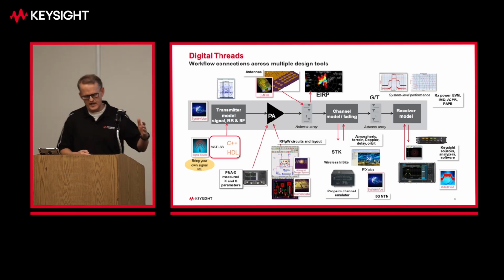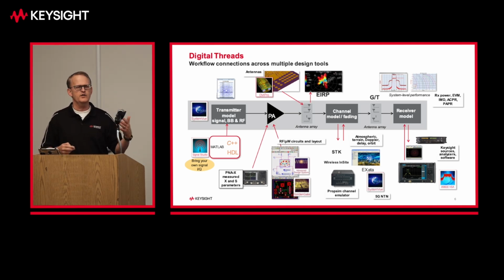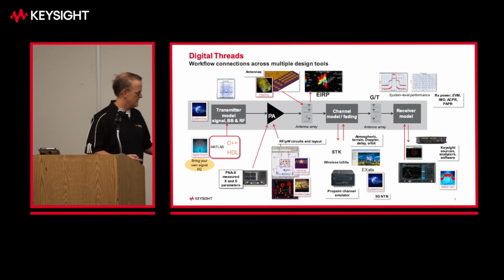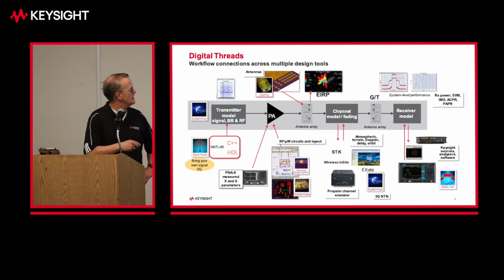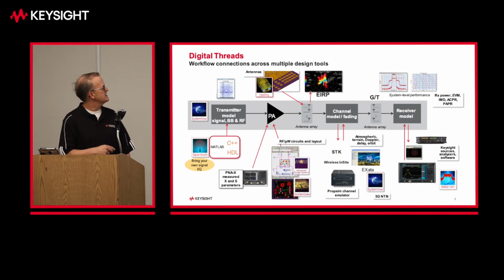This is kind of walking you through a little bit on the workflow. So you are going to have typically a setup like this, right? Where you have baseband, you have the transmitter, you have some sort of front-end electronics, you have a transmitter phase array or an antenna, you have a channel, a dynamic channel with multiple things going on in there. Maybe it's a digital emission, maybe you've got interference going on in there. You've got a receive array antenna, and then you've got the receiver. And each of these blocks, they're all in this gray block because SystemVue can model that.